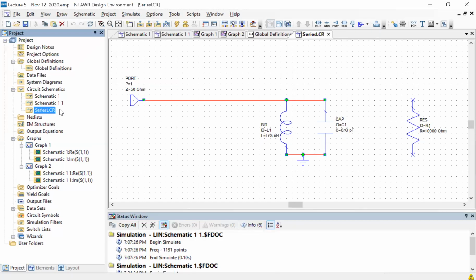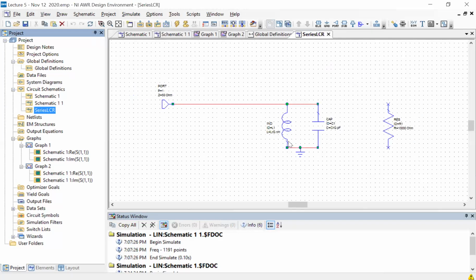So in most of the things, at least from the research point of view, the kind of systems we make are almost always modeled best by parallel LCRs. But it's good to know the series one as well, because at least at lower frequencies, and if you have done experiments in your undergraduate laboratory on any kind of LCR circuit, it usually tends to be a series LCR. And we had discussed this in the beginning from the point of view of what the role of the resistor is, because it's somehow counterintuitive for parallel that the bigger the resistor, the less the dissipation, right?